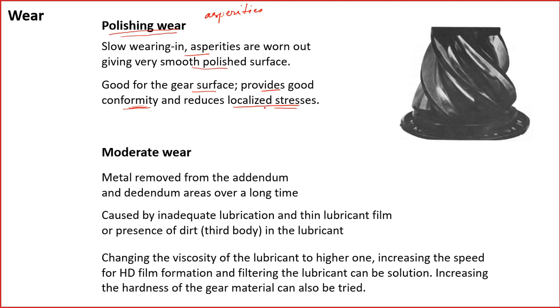So initial polishing wear is good, but during the polishing wear you can also understand if there is a misalignment, because misalignment will lead to an irregular type of polishing.